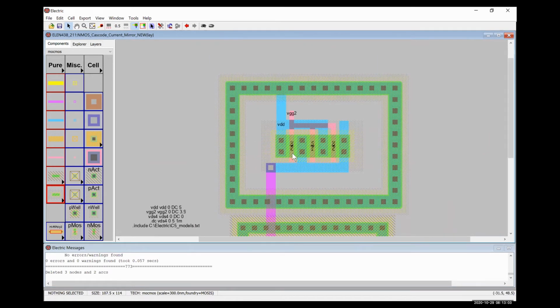Another thing that I've done, I should mention this. You can't really see it on the drawing, but I've gone through and renamed all of my transistors. With 7 transistors, 3 PMOS transistors technically forming one larger PMOS transistor, and then 4 NMOS transistors, it was getting cumbersome trying to remember what was what. So my PMOS transistor has an M5A for the leftmost one, M5B for the middle, and M5C, because we labeled that transistor M5 in our original diagram.